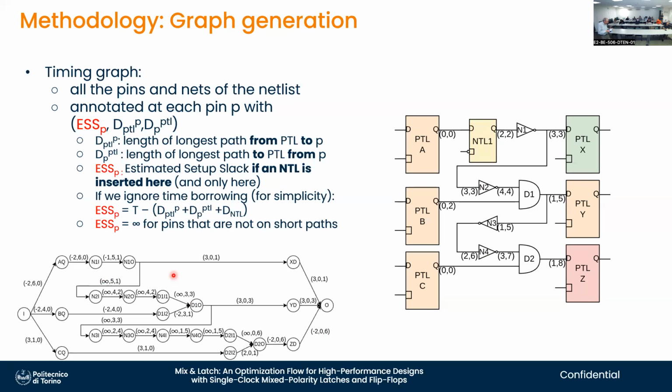We always want our customers in the bank to arrive at the end in front of the next double door or go through door, simple door, with enough time to be comfortable, not to be rushed. Or even worse, we don't want it to be with negative slack, which means he arrives late or she arrives late. Okay? So we want to have the estimated setup slack to be always positive for the selected locations where we insert those latches. But we compute that for every potential location.